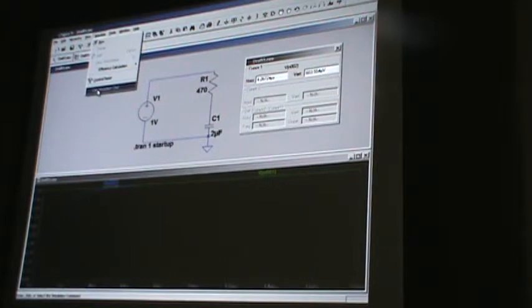Yes. Here you see. This looks better. You can zoom in and you can see the curve as the capacitor voltage charges up towards the battery voltage. What did you do differently then? We had to start the simulation at 0 volts, so you can see the capacitor charge up. Okay. It was already charged up when he hit run, I guess. How do you change that under control? He's going up into an editor, and there's actually an option for start external simulation command. Yeah, that's under simulate.